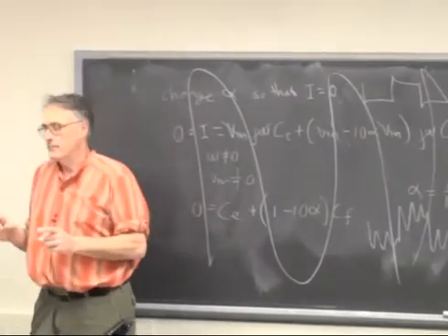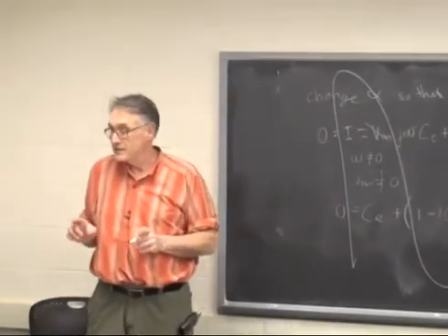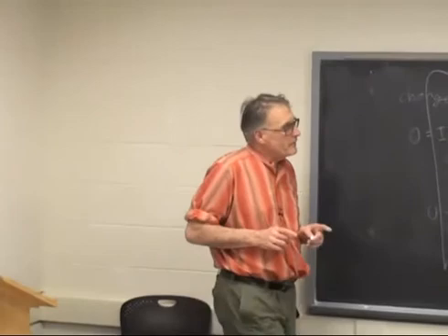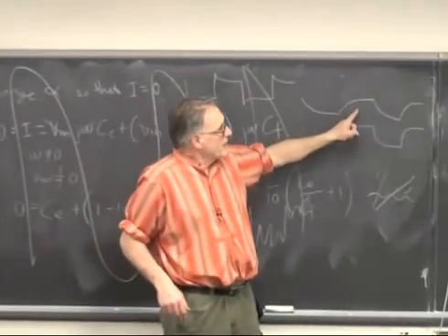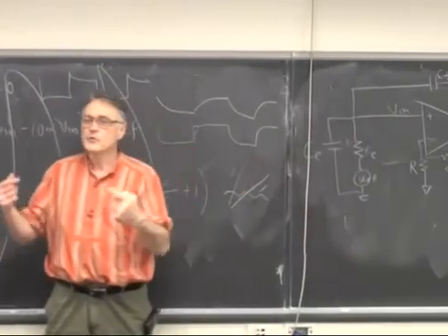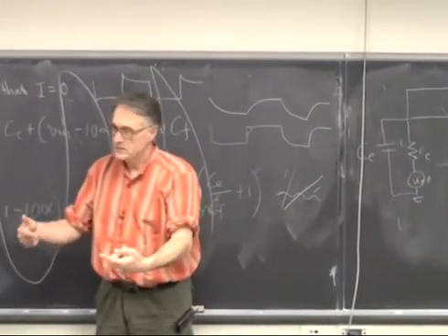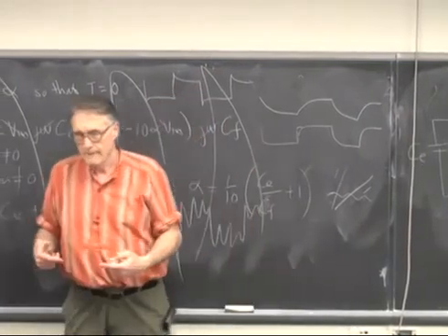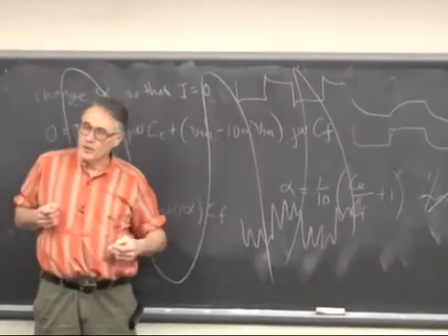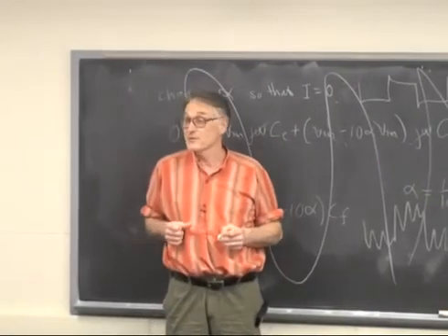I think the advantage is, I mean, this is an interesting question. I believe the answer is that if you take the output of this and then put it through a second op-amp, you have two op-amps' worth of noise, whereas this way you have one op-amp's worth of noise. But that would be interesting to work through in detail. I don't know the answer on that one.